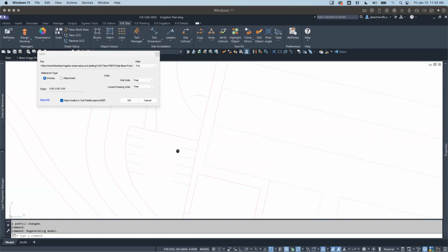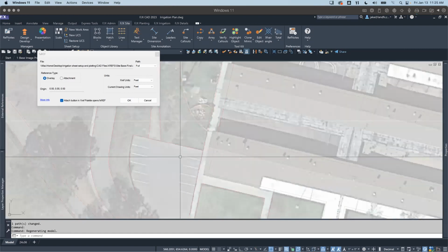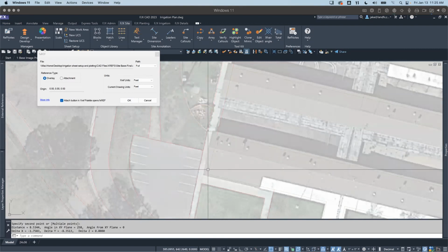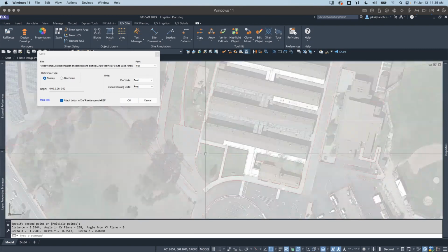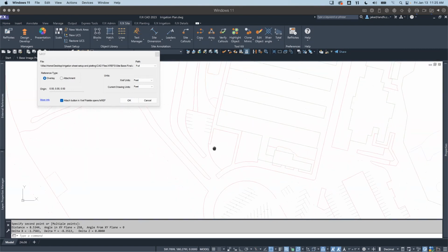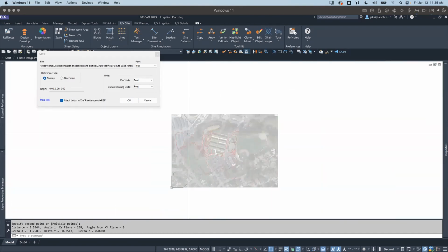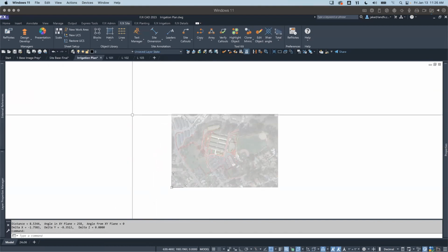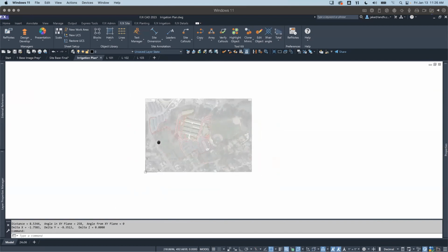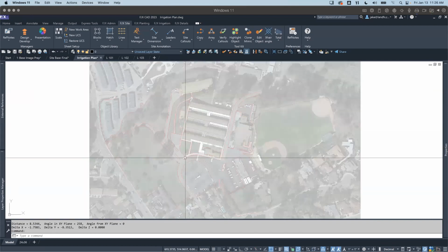And that's another really cool reason FXRef is nice, because you can validate, you can run different commands and test how things are actually sized and run some verification before actually allowing it to be XREF'd into your drawing. So everything seems to be good. It cross-checks me on everything is set up, and I'm going to say okay. So now I'm ready to design, right?